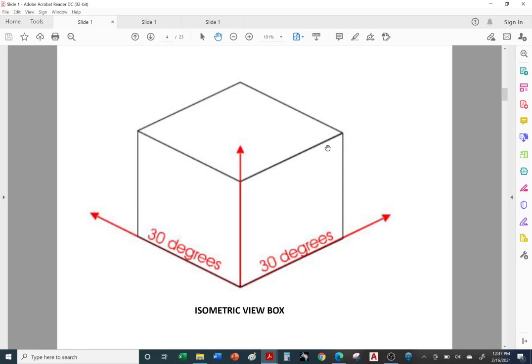You typically start with the box. It's a rectangular box. It doesn't necessarily have to be squared. Think of a rectangular prism. We're going to use 30-degree angles to draw our box. Imagine you're making this custom-fit box for your part, like a glove to a hand.